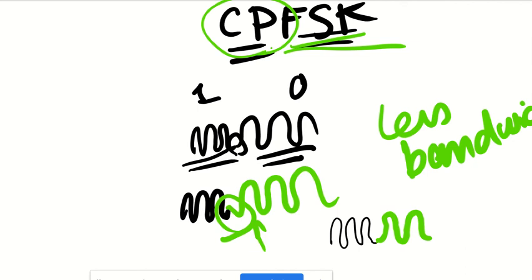And it's not only for FSK. Even for OOK, on-off keying that I talked about before, it's important to have a coherent signal to avoid abrupt changes. Even for ASK, amplitude shift keying that I talked about before. They have techniques to get rid of these glitches and make sure the signal is coherent. If they apply those techniques, it's called coherent phase, which makes sense, right?